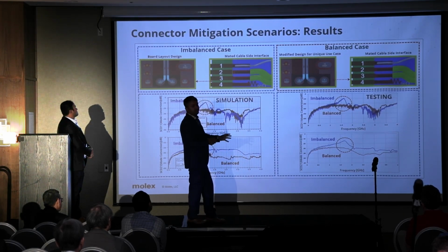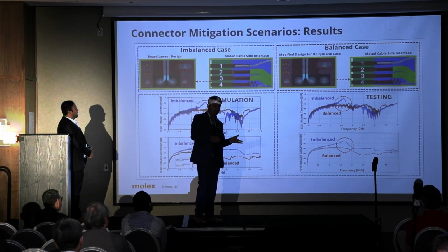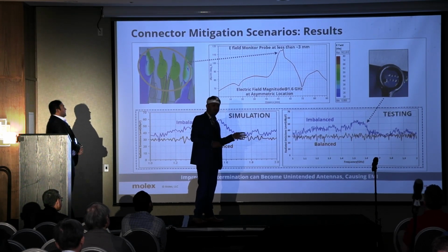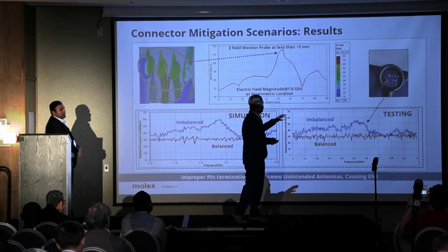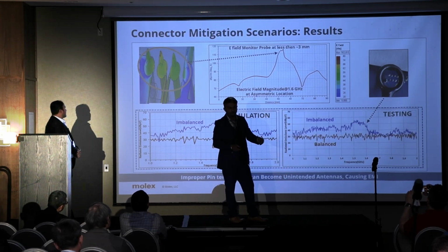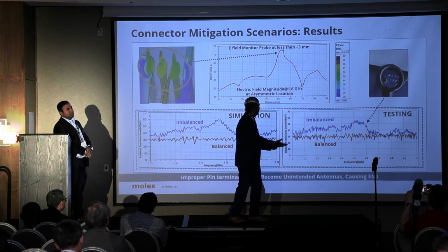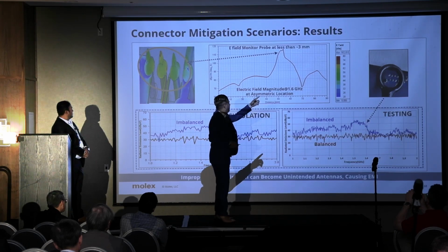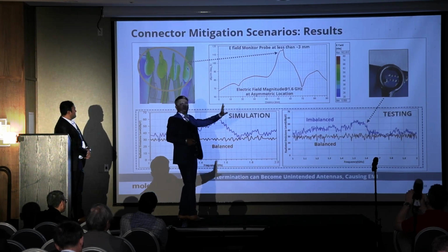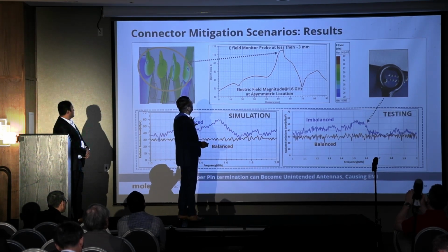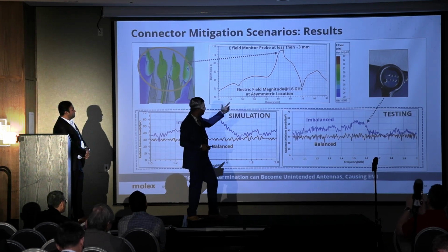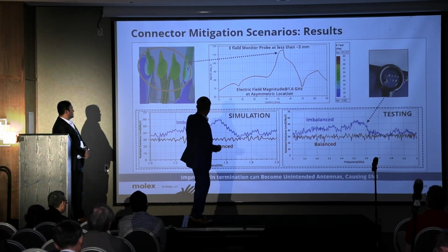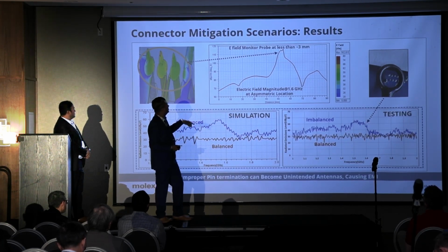And we also did radiated emission testing and a simulation, which I'll be showing in the next slide. So here, in the lab, we used a near field probe above the area of interest where pin 4 is present, right? And this is the simulation. We replicated the same thing in the simulation. So we created an antenna that replicates the near field probe. We tried to maintain the same distance. And so the left-hand side is the simulation result and the right-hand side is the testing result.